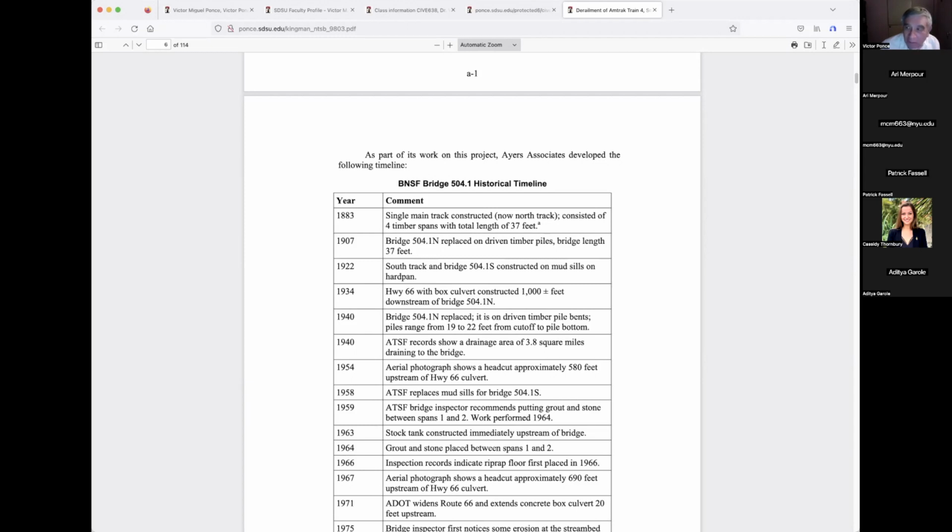They're timber pile bridges. Why is that? Because that area of Arizona is so flat that there is no concentration of streams. So the streams are all over the place. It's flat, and so you never know when and how it's going to rain. In this case, it rained. Now, somebody could argue that most likely the 100-year flood hit this bridge, and it couldn't take it, and it failed. Well, no. The calculations have shown that the 5-year flood is the one that hit the bridge. And this report says that. It was not that big.